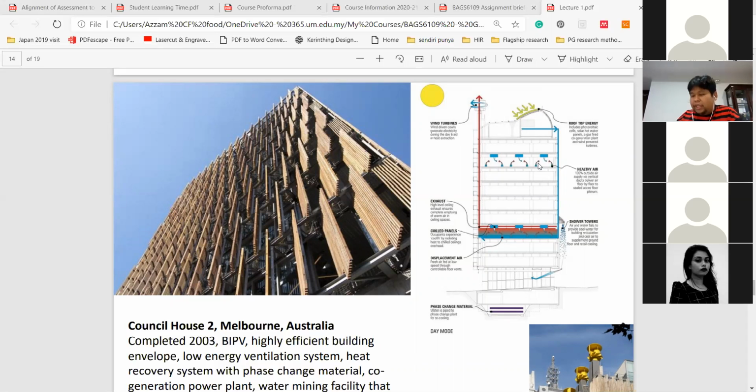It's got this thing which is what we call the, what are the fins? Let me see. Okay, that one is in another lecture. I forgot the term already. It's actually a metal fin that is fitted to the underside of your ceiling. In the metal fin, you've got cold water running in it, and the metal fin will absorb all the heat.